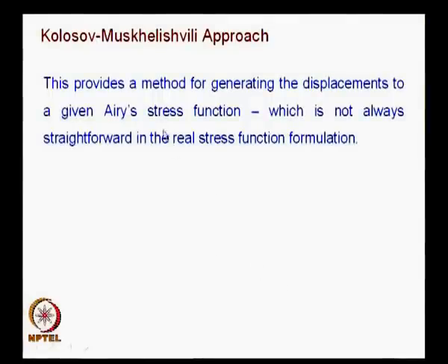And another advantage of this Kolosov-Mushkelishvili approach is this method provides a simpler way to calculate the displacement. For any given Airy stress function, if I identify the complex potentials, I could find out the displacement in a straightforward manner.